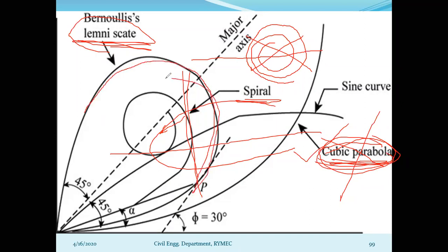When this one is taken, how does it happen? Here in this curve you are going to see both the cases. Which are both the cases? It means you are going to see that the centrifugal force and the self weight of your vehicle can be balanced. Here it can be done. Some people will go for the cubic parabola and some will go with your lemniscate parabola. I will show you which one in the next slide.